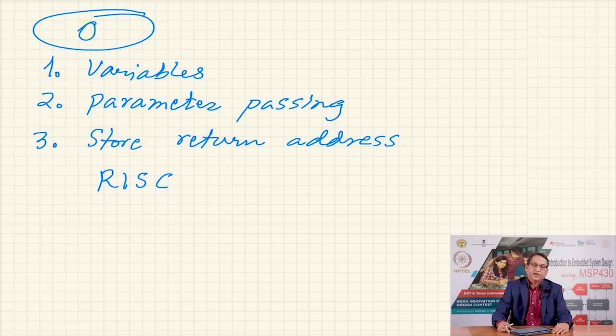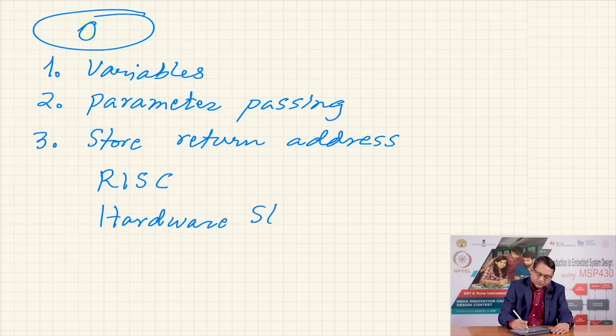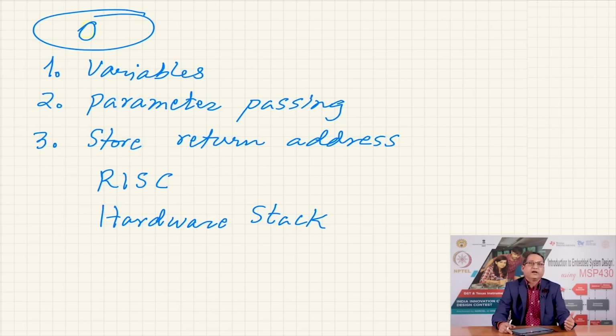In such cases where the microcontroller does not have any SRAM, instead of using RAM for the purpose of a stack, such microcontrollers offer what is called a hardware stack. What is a hardware stack? Meaning there is a dedicated storage memory specifically for the purpose of storing return addresses. Now, if you have a regular microcontroller with some amount of RAM, the entire RAM could be used for storing return addresses.